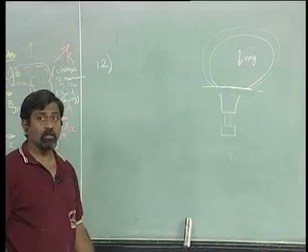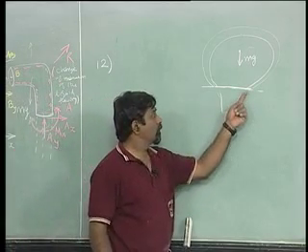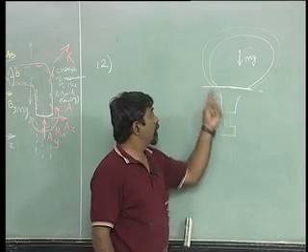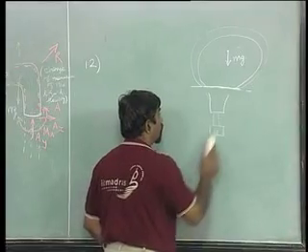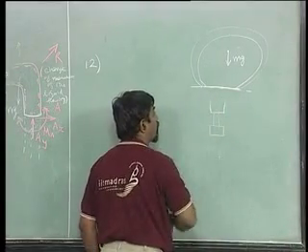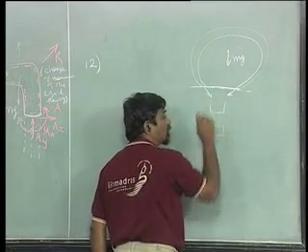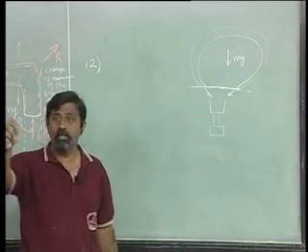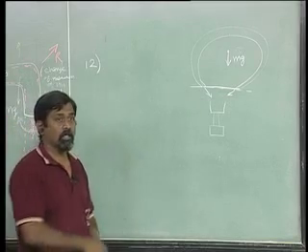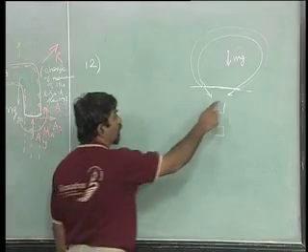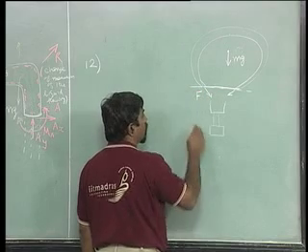Apart from that, there are many contact forces. One contact force arises due to the bottom part and the top part of the membranes interacting. Okay. And therefore, if I remove this bottom part, there should be an interaction force along this direction. Remember, it is a membrane, which means it does not resist any forces along the other directions, and therefore, I will have interactions of this sort. Let us call this F per unit length.